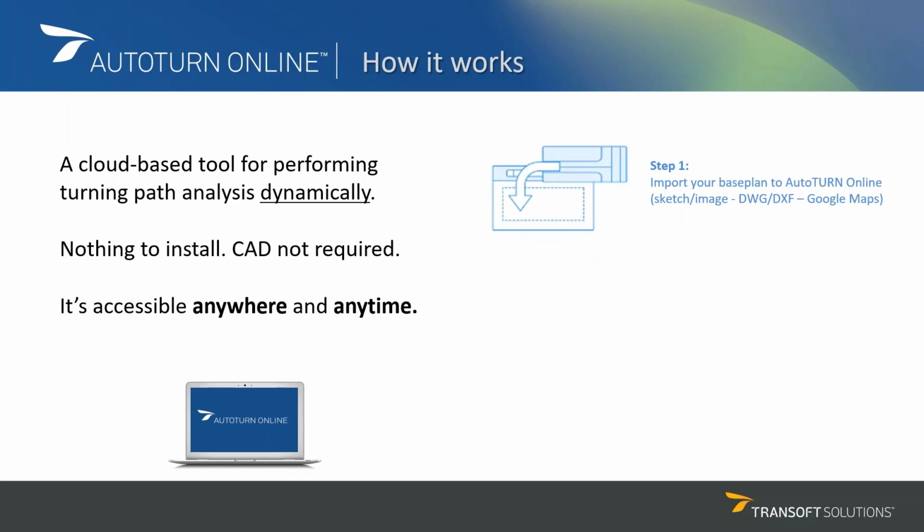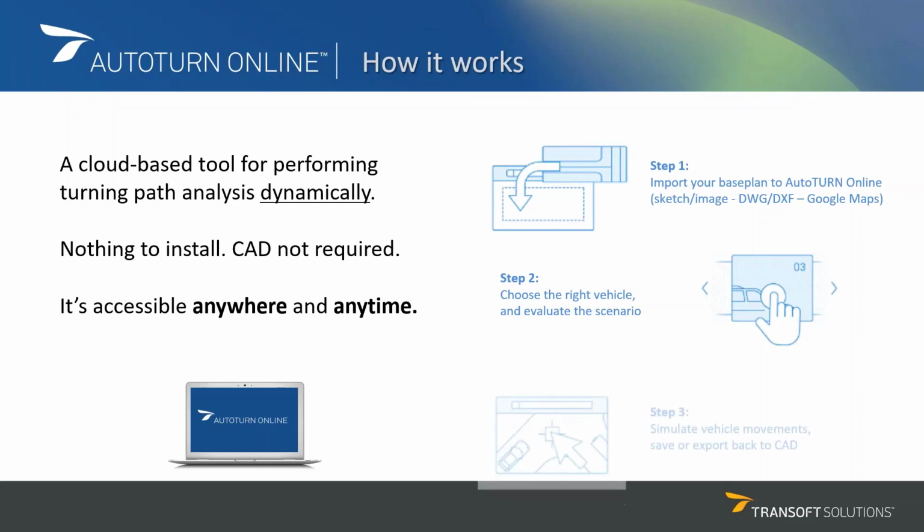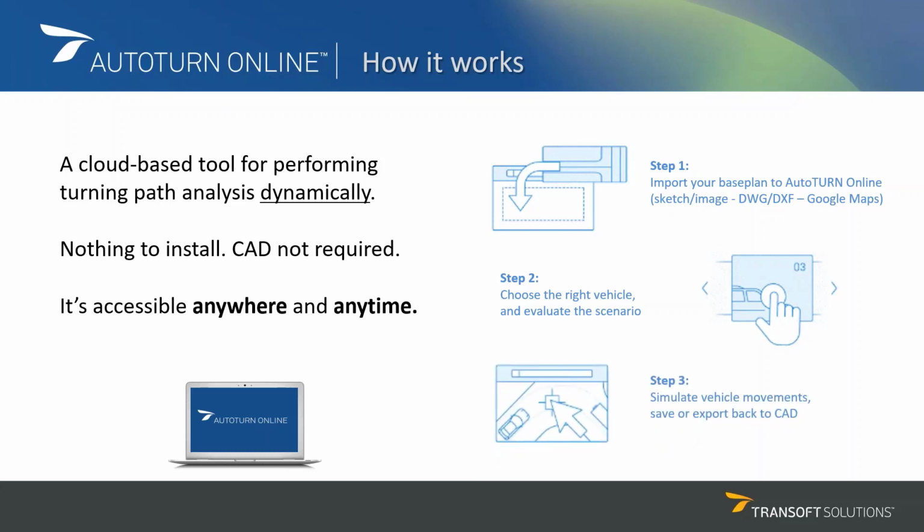So in step 1, you can import your base plan, whether it's a sketch or aerial image, DWG or DXF file, or even terrain information coming straight out of Google Maps. Then in the next step, you choose the right design vehicle for the scenario. And in the last step, you actually will do the simulations in forward or reverse. Then you can save these simulations back to a drawing. You can export them back to CAD and overlay them in the original drawing file.